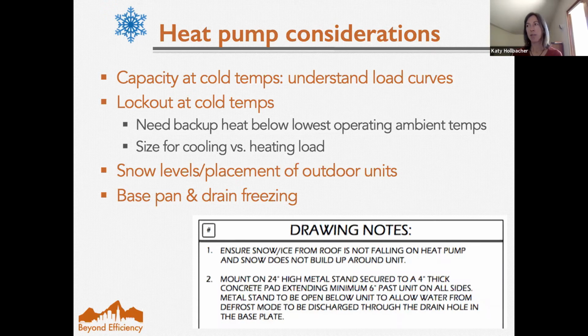The challenge we can have with them in our designs, which is actually less of an issue here just because it's colder, is that the indoor units have their rated output, and if your load in a space is much lower, but you can only go so low with a certain terminal unit, you can get into cycling of the unit, which is not good.